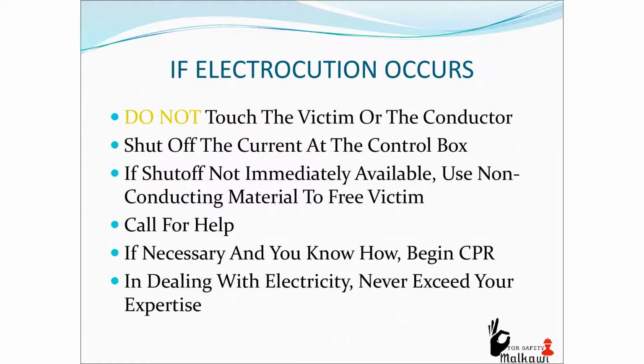If electrocution occurs, do not touch the victim or the conductor. Shut off the current at the control box. If shut off is not immediately available, use non-conducting material to free the victim. Call for help. If necessary and you know how, begin CPR. In dealing with electricity, never exceed your expertise.